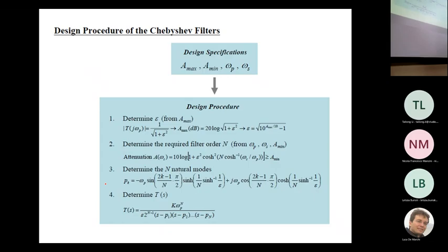Once you find this chain of second order transfer functions, you select one of the possible strategies to implement the second order transfer function with circuit topologies. So you can pick the Sallen-Key topology, the Tow-Thomas topology, LCR, whatever topology you prefer.